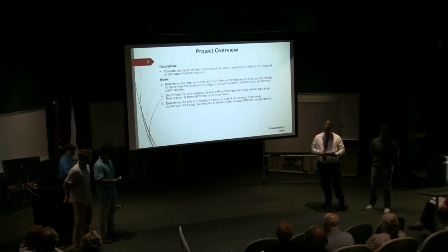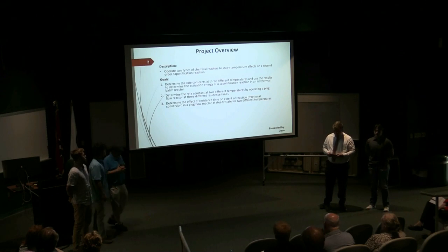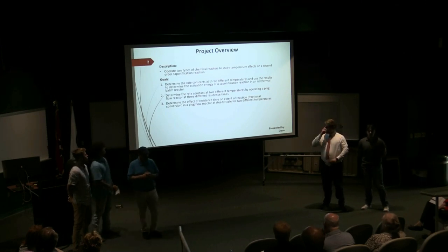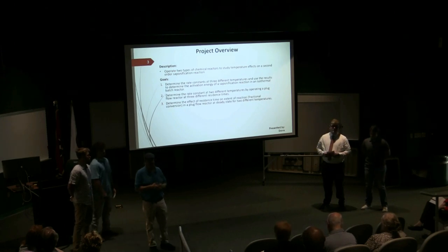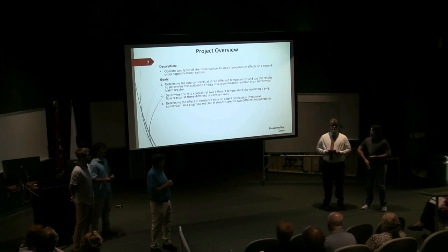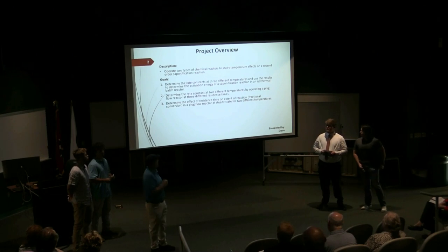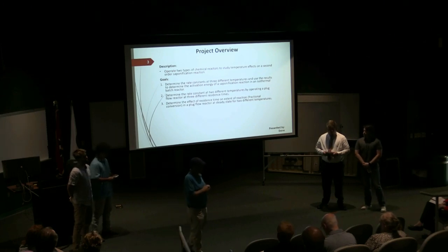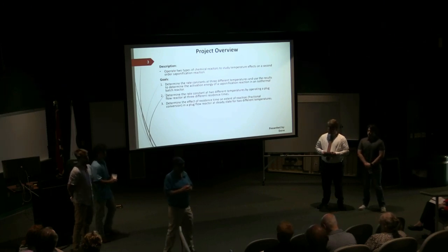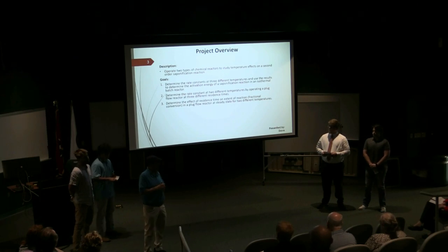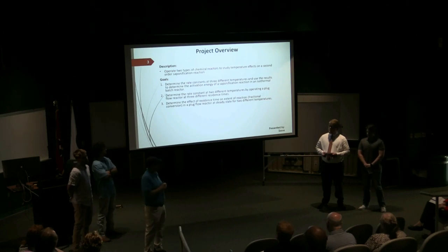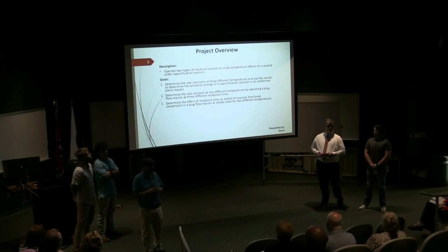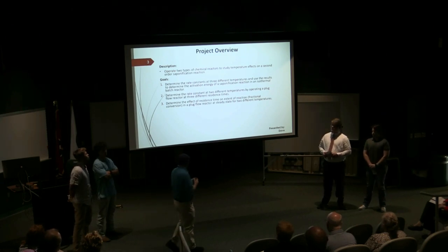So in this, our project plan was to operate two different types of reactor, a batch reactor and a plug flow reactor, and to look at activation energy as well as rate constants and calculate those for both types. In the plug flow, we also looked at the effective residence time on extended reaction for fractional conversion.